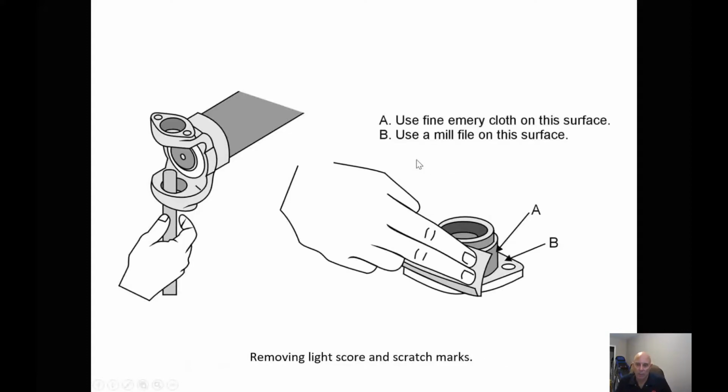When we're installing a bearing cap, okay, so we've taken it apart, we had to change the seal on the front diff. So taking a piece of emery cloth and cleaning up inside the yoke and cleaning off the cap, putting a little bit of never seize on the cap, and then reinstalling it. Now, if A and B come apart, it's garbage because the cap's going to spin, it's going to wear out the yoke, and then it's going to be no good.